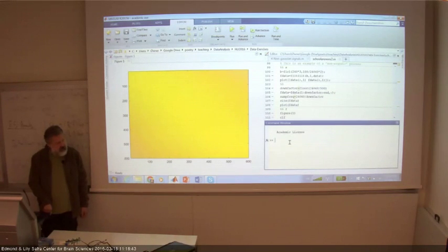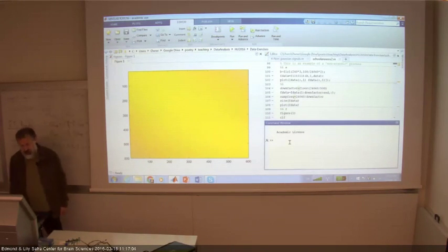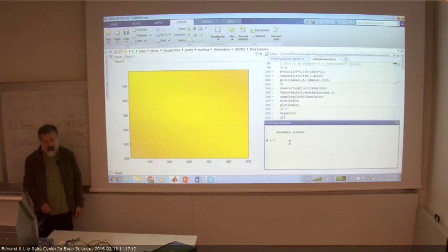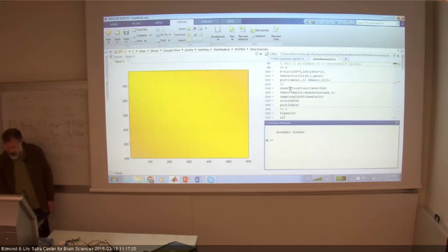One consequence is that for these segments, very often when we talk about averages, we think that we can take average across trials and average across time, and it would give us the same answer. This is an example of a process in which this can't be done. Now processes for which average across time and across samples are the same are called ergodic processes. And when we say stationarity, usually we mean ergodicity. We mean this stronger property. This is an example of a non-ergodic process, but this is a fine point.